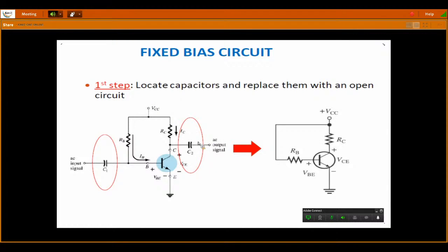We connected one more capacitor, and this capacitor blocks the DC signal which is present in the output. The additional DC signal present in the output will be blocked by this coupling capacitor, leaving a pure AC signal with a zero reference level, which will vary up to Vm and down to a minimum of minus Vm.